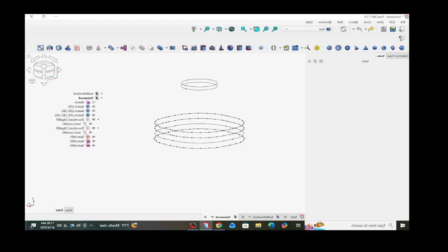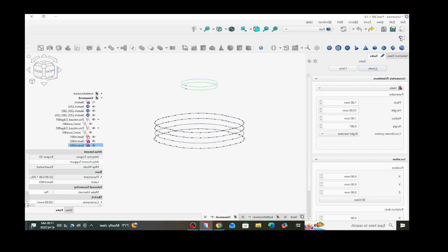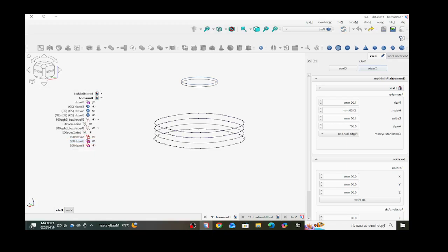I'm going to create a primitive shape, which in this case is a helix. So the radius of it does not matter too much. I'm going to put it on the outside of the part. The height matters a lot. You have to match it to the total height of all your profiles. So that's 53 millimeters. Actually, it's 55 millimeters. I'm going to raise this one up above it. 2, 3, 4, 5. Good. So the height of the helix will be 55 millimeters.